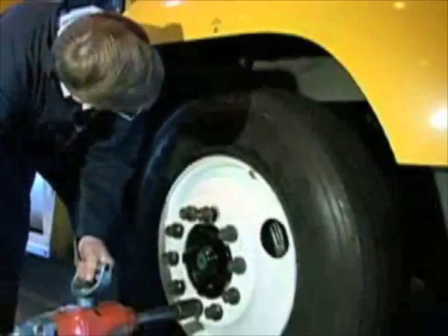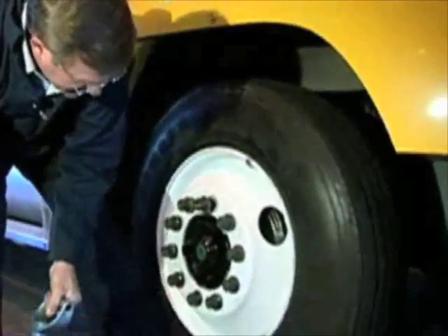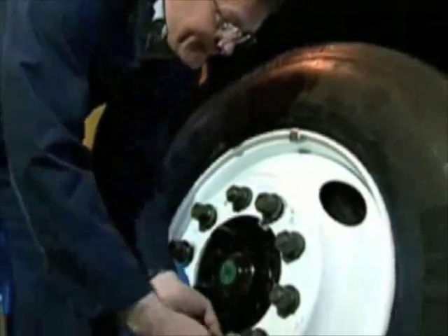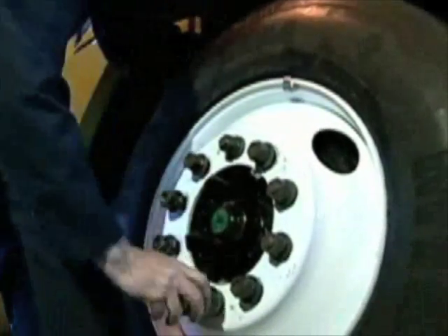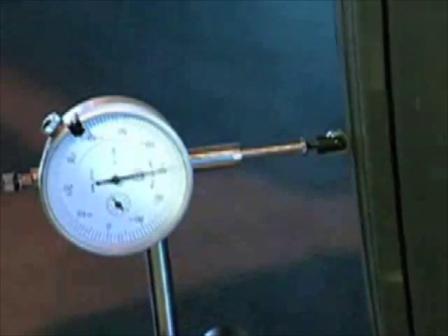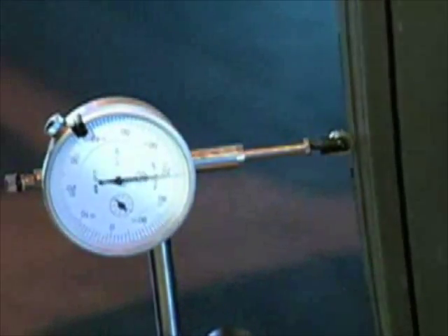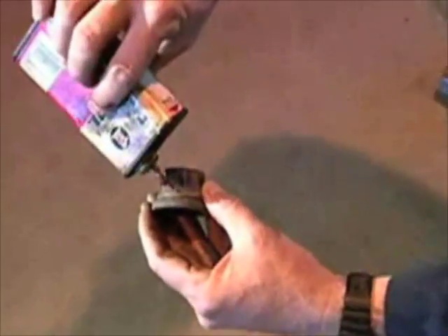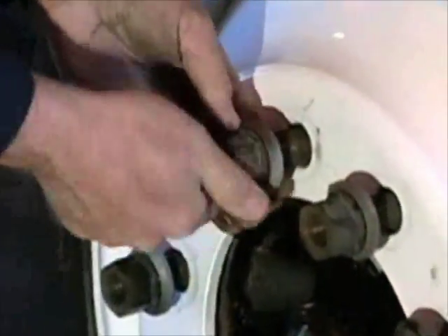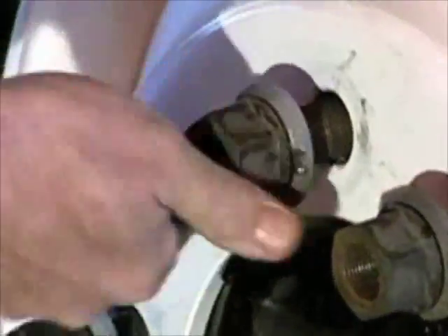Loosen the nuts and allow the assembly to drop. Hand tighten the 12 o'clock nut first, then hand tighten a few additional nuts to hold this adjustment in position. Now recheck the radial and lateral runout to see if an improvement was made. Note, be sure to add 1 or 2 drops of oil between the nut and the flange washer to facilitate correct torquing in accordance with manufacturer's specs.